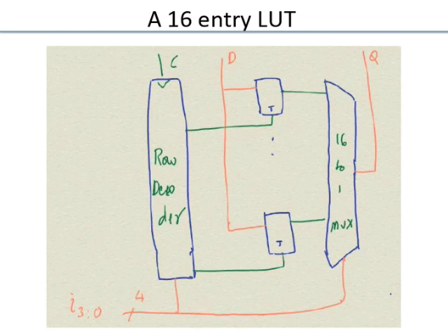But then we may not have sync between when to write and the data D. You have to maintain that sync. That is not that hard to do. Write enable and D can come out of the same clock. So you will have a clock, because this will all be pipelined systems. There'll be a clock which will give the write enable and the data for that write enable, and the address to which you want to write. Everything will be synchronous. So there'll be a flop which is not shown.